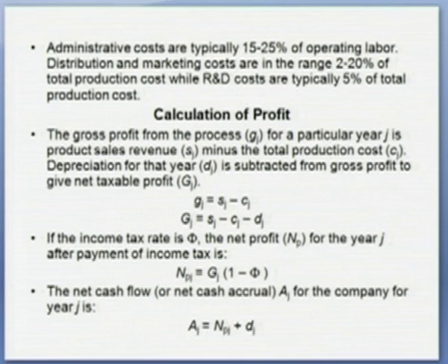Now, this completes our discussion on the project cost estimate. We have seen a very detailed discussion. We first found out what the cost components were and how we categorize the cost. First is the total capital investment, which is fixed capital plus working capital, then the total production cost.